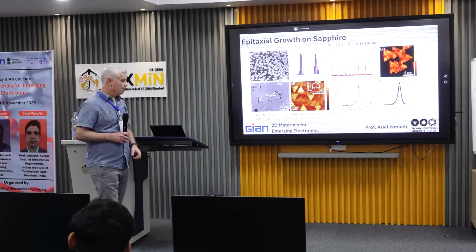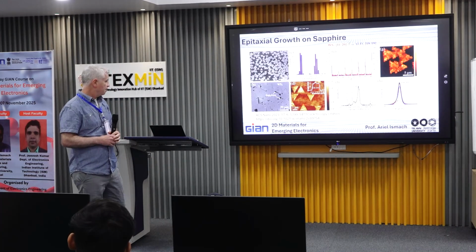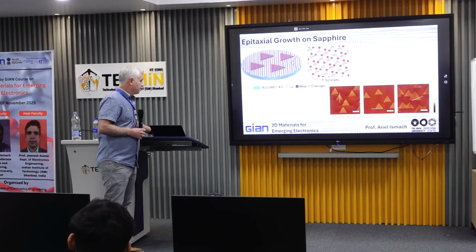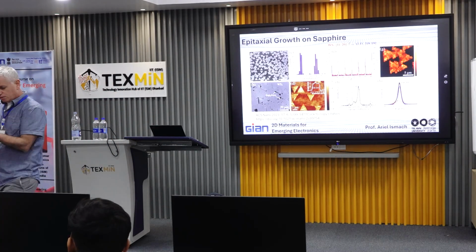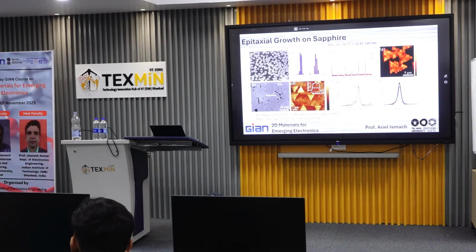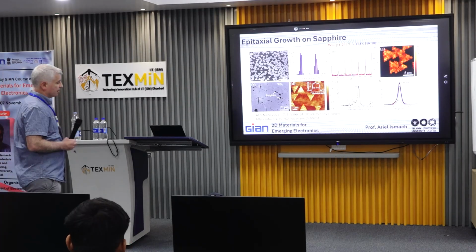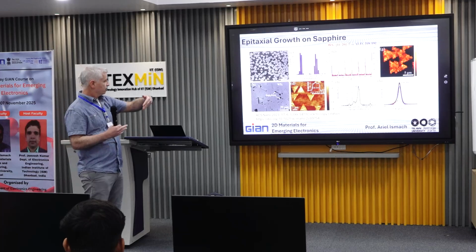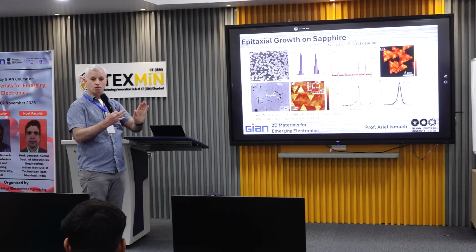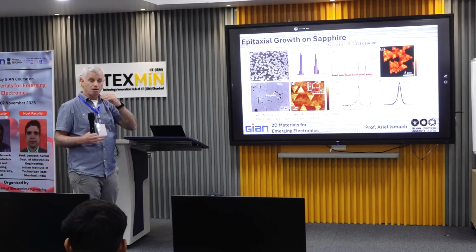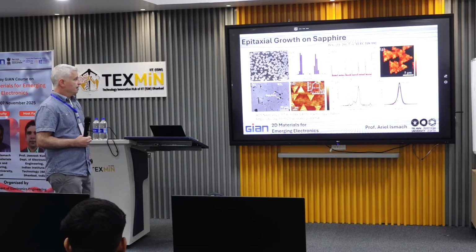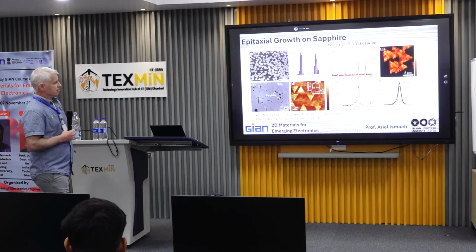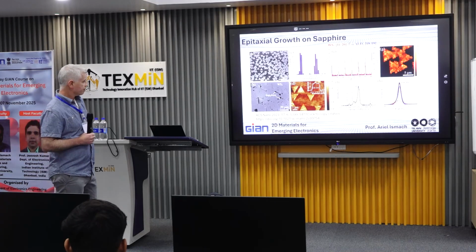Now this is a problem, assuming that these films should coalesce together and form a continuous single crystal film. When you have these two rotated crystals, it is a problem because they will make line defects. And this happens, of course, because of the surface of the sapphire.